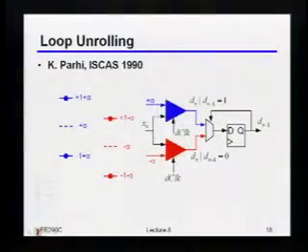But the last thing we ended up on was saying that, if you really want to push it, and if you don't want to have to move all the way into CML, or in fact even beyond certain data rates, even in CML, you might have to do this. There's this basic idea of trying to not really close the loop, but instead doing what's called a loop unrolling technique. We talked about this a bit last time, but just to make sure that it's really clear, let's say that we really couldn't deal with that very first tap.